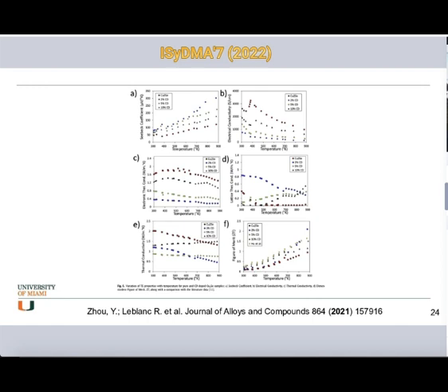For figure E, it can also be demonstrated that the carbon dust doping alters the thermal conductivity trend from decreasing to increasing over temperature. And a low dopant ratio yields, we would say, the declining trend. And again, that means the figure of merit has been improved using our carbon dust in each of these figures.